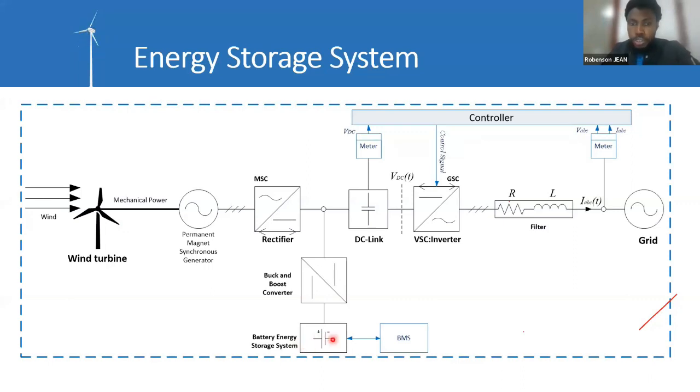And in order to do this, through my battery management system, I will activate the boost side. Therefore, if the output voltage of my battery storage system is 100 volt, I will step up the voltage so I can synchronize at this boost that is at the level of 300 volt. Therefore, the conversion ratio of my boost converter should be 3 times. So this is how I can implement a battery energy storage system globally.